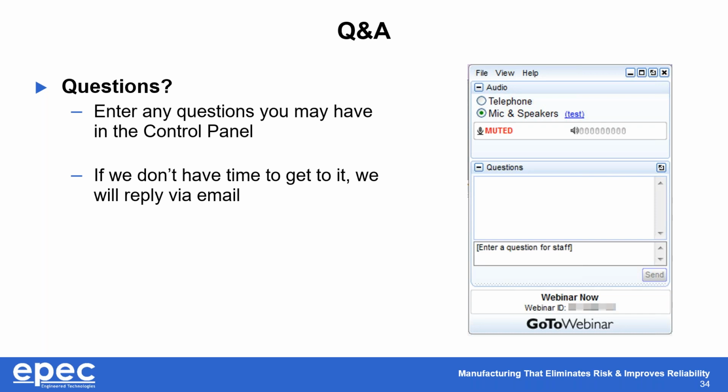The second thing is that typically when we do drilling in printed circuit board manufacturing, we like to stack product up in the drill. So you'll stack four boards up and you'll drill all four at once without changing it out. Well, typically there's a couple things. One's called drill wander. So you really on Class 3 boards have to be careful, and many times you don't stack it up because you don't want the drill wander to create breakout. Along with that, you've got to slow it down because there's this feature called rapid runout. If the drill bit isn't sharp enough and the bit hits the actual copper itself and then begins to shoot off in one of the directions and outside. So it really costs us a little bit more to produce.